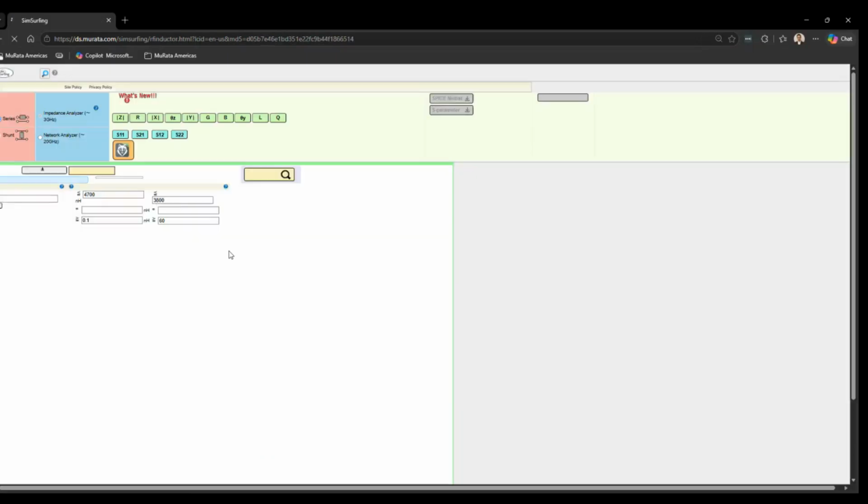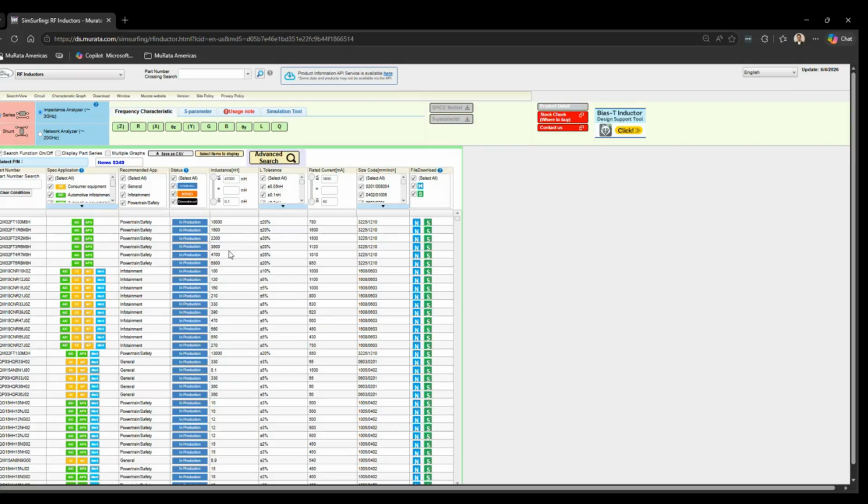Now let's jump into, say, the RF inductors. Like with the caps, where DC biasing mattered for class 2 dielectric, for an RF inductor you're worried about your SRF, self-resonant frequency. So you might want to look at parameters or different overlay graphs to determine that SRF, to make sure it'll work as an inductor up until that frequency.